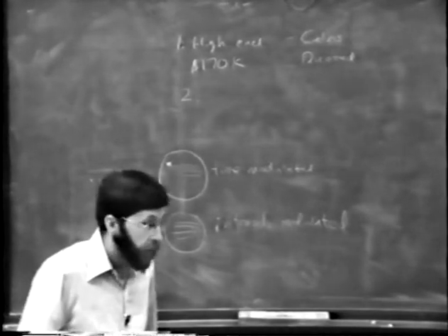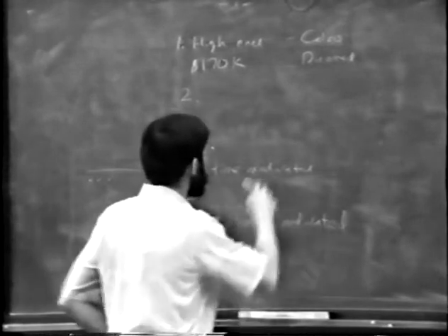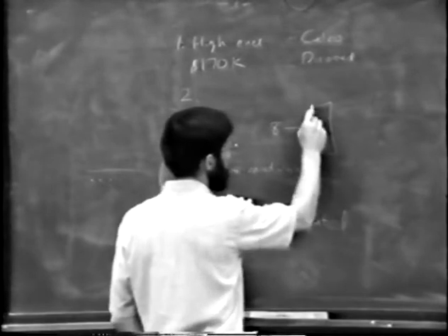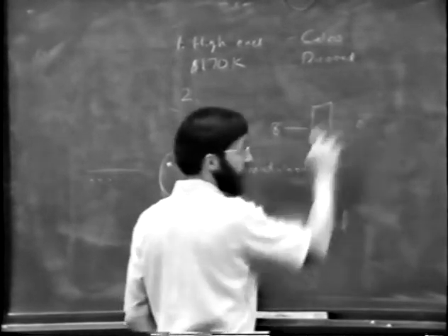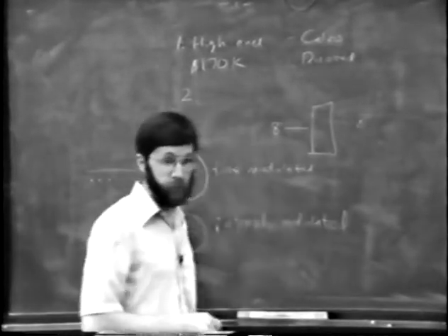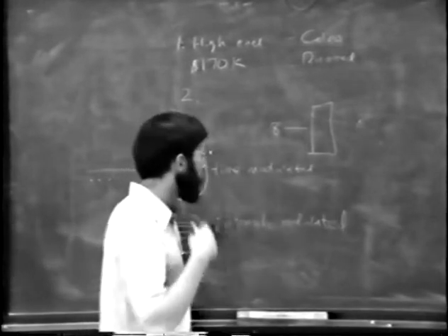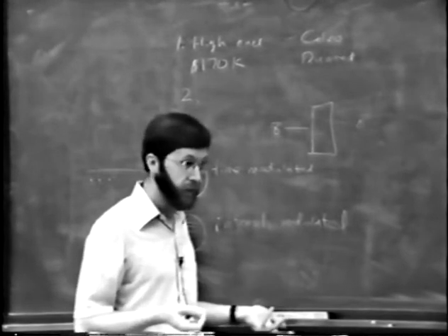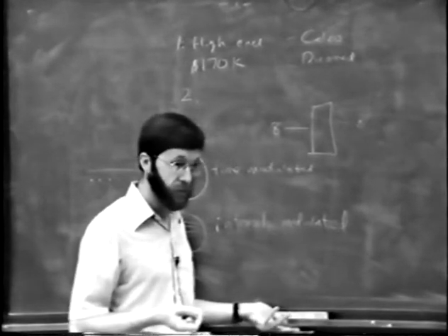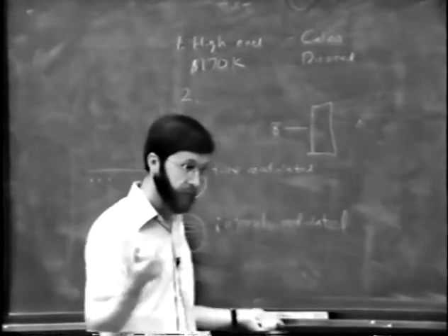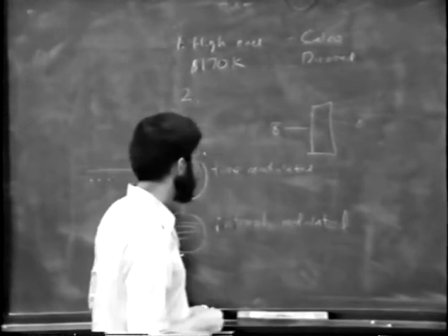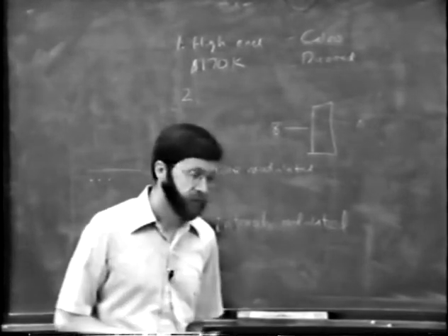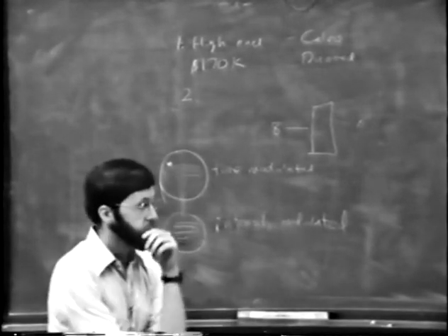Now, the way this box works is you give it an 8-bit intensity and it goes into a table lookup to convert it to a different 8 bits, but it's 8 bits in and 8 bits out. So that's all you've got in this thing. Well, if you put in your 8 bits and you fully expose it, you find that your dark end is overexposed. And if you bring the dark end down, you haven't fully exposed the thing. That required some tweaking on their part. But the unit wasn't nearly fast enough. It was still a minute per picture.